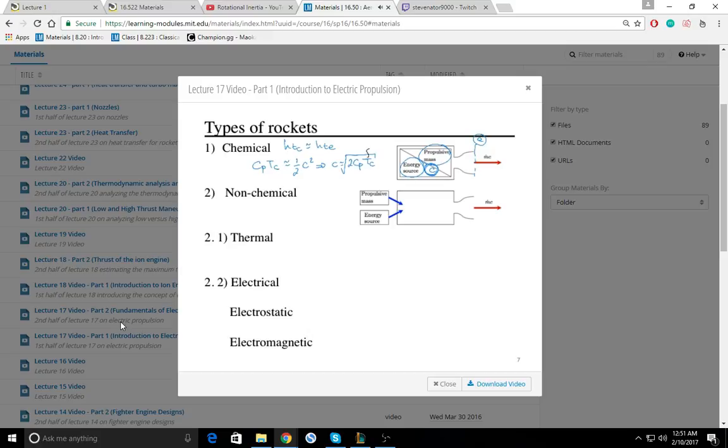So the specific impulse typically, if we have 2,000 Kelvin for combustion temperature, the Cp of the order of 1,000 joules per kilogram Kelvin, then the exhaust velocity is around 2,000 meters per second, which in terms of the specific impulse is a factor of 10 lower by the gravity constant, so it's around 200 seconds. So that's the typical specific impulse of a chemical propulsion system.